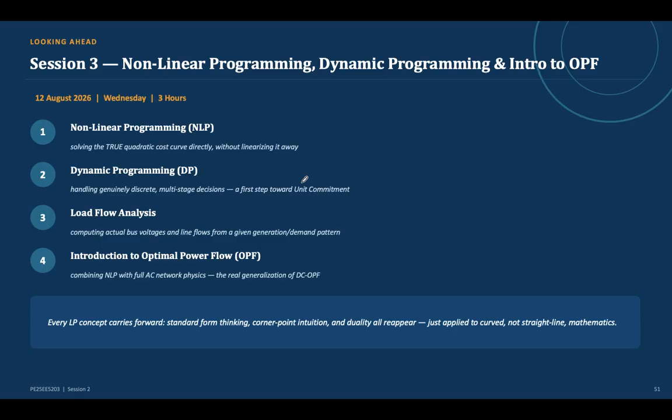If you remember only one conceptual chain from this class, remember this. A real engineering problem is first translated into a mathematical model, right? The quality of the optimization result depends on the quality of the model. LP provides a particularly powerful framework when the objective and constraints can be represented linearly. In a power system, linearization allows us to trade a controlled amount of modeling accuracy for computational speed and scalability, right? That is the real reason linear programming matters in power system optimization.